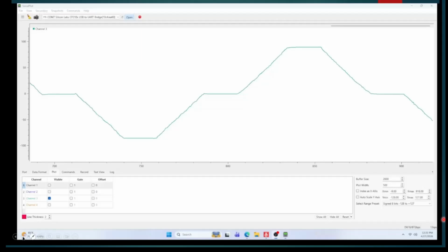So I think this gives you a good idea of what they mean when they say with the accelerometer you have a lot of noise, because if the system shakes a little bit, that's going to be reflected in the accelerometer. And then you get an idea of how nice the output is from the gyroscope, except that the gyroscope with time drifts.